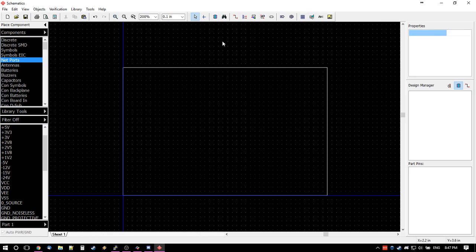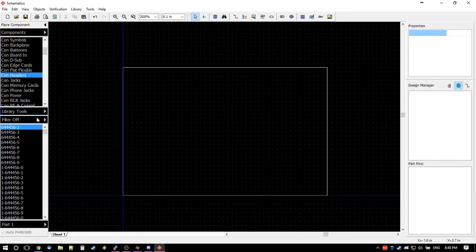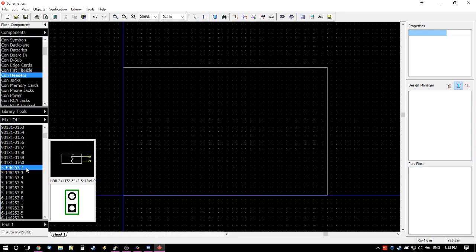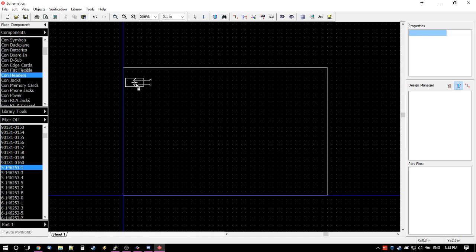All right, so now we're going to do things a bit more properly, the way you would actually do it professionally. So the first thing we're going to do is, again, put a header on the board. So we're going to go to headers, and we're going to place that same part, 5146253-1. So we're going to place that up in the upper left here.